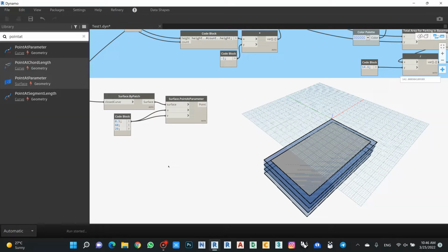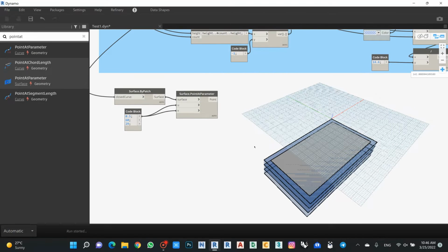In this case, I will create a rectangle, and the rectangle should not exceed the length at 60 and the width at 29. So I will create it as a number slider and then connect it to these points that I created, so I can make the plan for now.